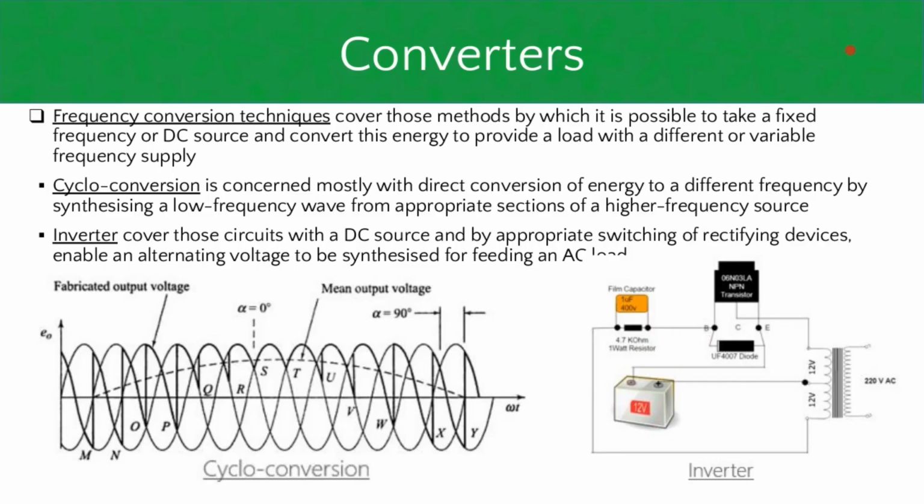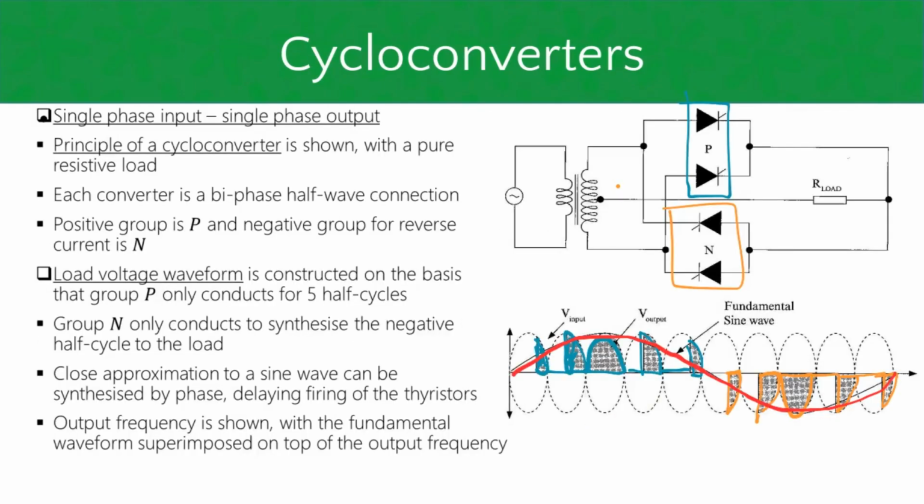If I can quickly go back here, you will see there is a basic diagram here of an inverter setup. So is this an inverter? Yes, kind of. A very basic one, but basically an inverter you can use to increase or decrease the frequency and thus control your AC machine's speed. That's actually how you can control the speed of an AC machine, by changing the frequency. You're not really going to change the speed by changing the voltage.